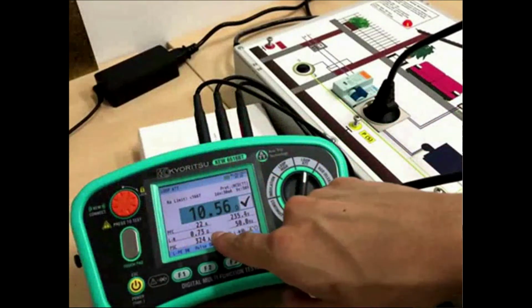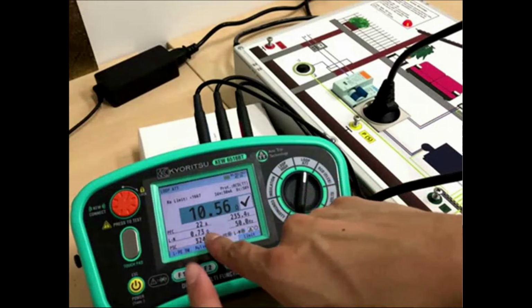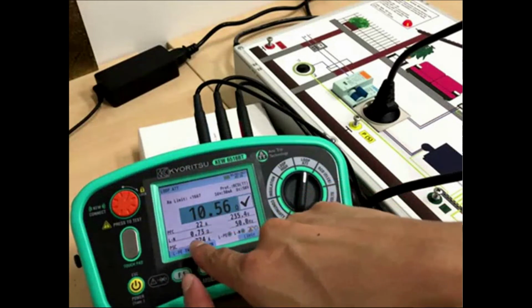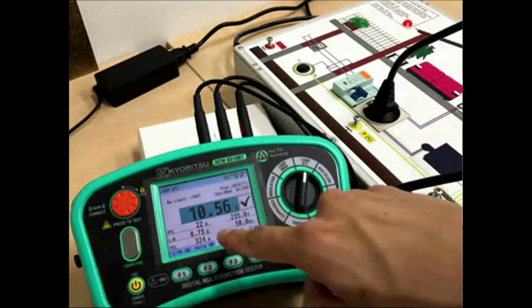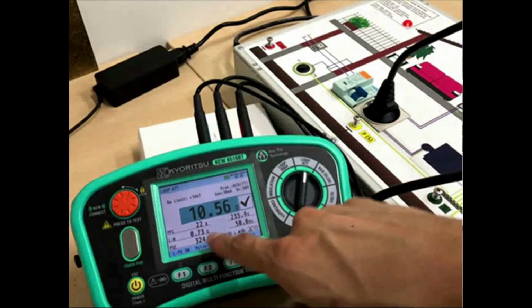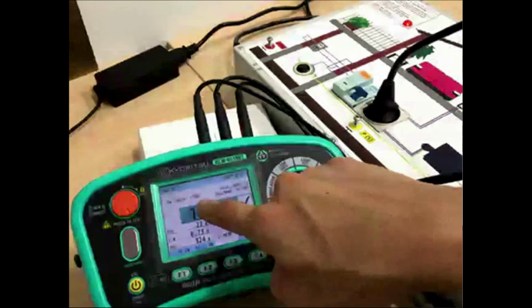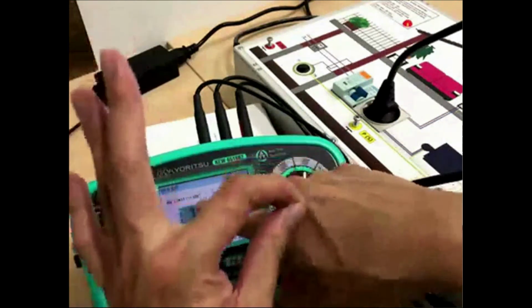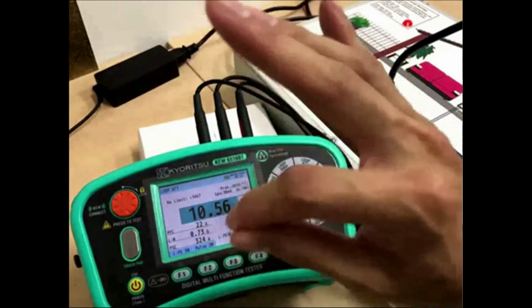Live and neutral is this one. This is the live-neutral impedance value. This is the short circuit value, when live and neutral touch each other and make a short circuit. So this impedance is below 1667, meaning to say your design of the impedance is safe to use. Pass. Okay, this engineer is okay.